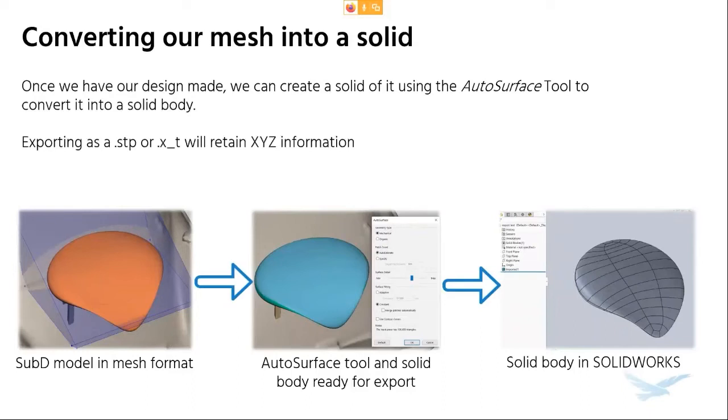And we can see in that right picture exactly how those NURB surfaces are laid out and stitched together. So you can see how we took that one really organic shape, made a bunch of spline lines and stitched them together, and we get something like that bottom right picture as a solid body.